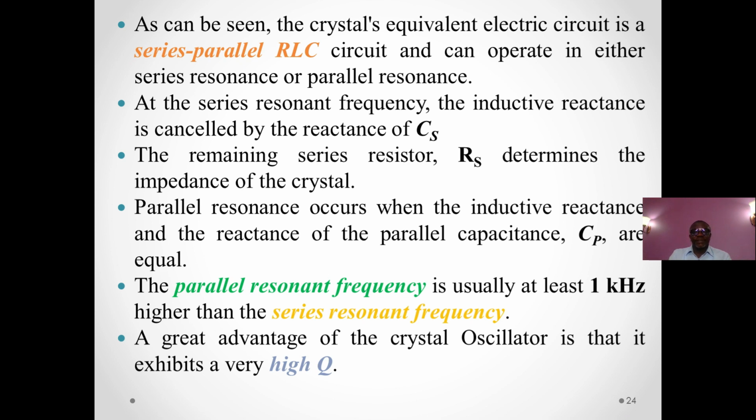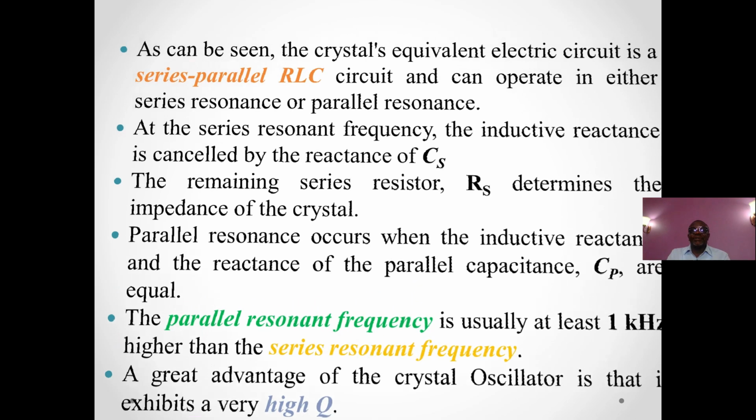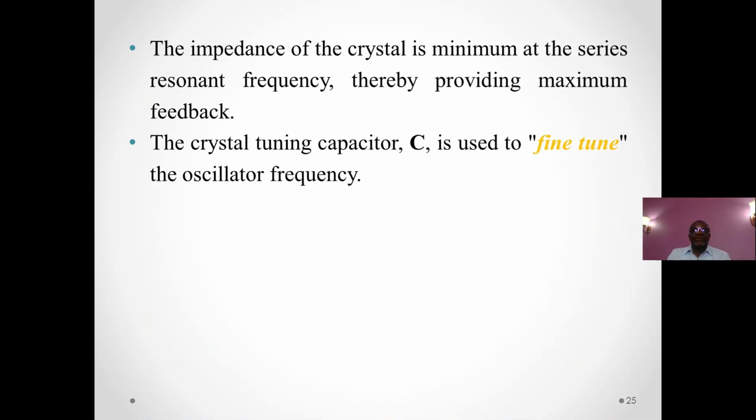The great advantage of the crystal oscillator is that it exhibits a very high Q factor, high quality factor. Impedance of the crystal is minimum at series resonance, thereby providing maximum feedback. The crystal tuning capacitor C is used to fine-tune the oscillator frequency.